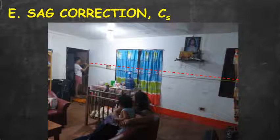So, sag is the difference between the tape reading and the horizontal distance between your support and can be determined by the following calculations. So, the magnitude of the errors depends on the weight actually of the tape and the unsupported distance and the applied pull or tension. Kung gaano ba natin ka-stretch, gaano ba karaming support ang meron. So, kung mas maraming support, konti lang yung sag. Okay. So, this is the error due to sag.